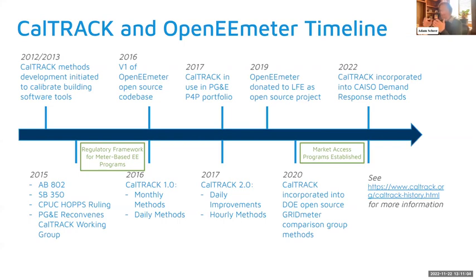So these were building simulation models where contractors could enter information about the home, the building, and what interventions they were doing, like changing the insulation from a certain thickness to another thickness, or putting in a new air conditioner with a SEER rating of X, Y, and Z. They had blower door tests, things like this. You could enter all of that information into a software tool, and it would predict the savings that you would achieve in a given project.